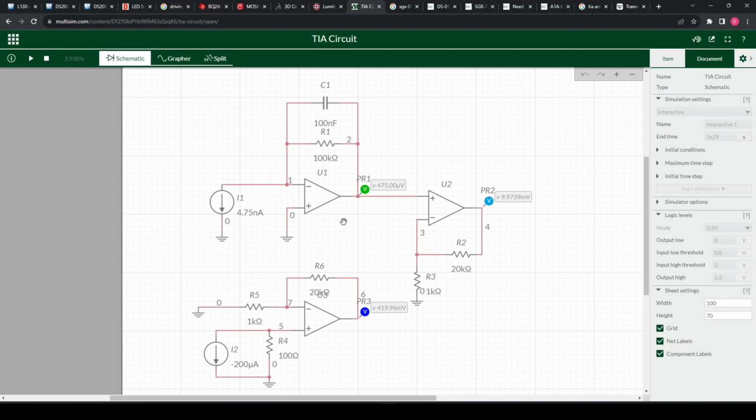At its core, it's just a fancy name for a current to voltage converter, really. So we have our current source here, we have our op amp, and we have our feedback resistor, which also acts as the gain resistor for our device. These are the main generic parts you'll see within a circuit like this one. Nothing else too much. This is just a standardized circuit. It would probably work with whatever, if you have a current source and you're trying to convert it. This is just a very standard thing.